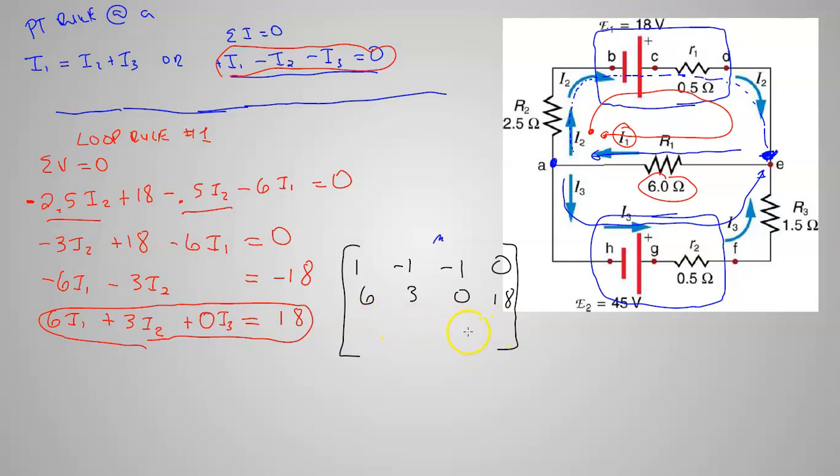And I need one more equation here to finish this thing out. So I got to apply the loop rule one more time. And again, I can pick any loop. I can go in any order, any direction. It is easier to go with the current. So we did the top loop here. We went around this way. Maybe the next thing we should do would be to come around this way. Go down the bottom branch and then back across the middle. So I'm going to draw that loop right here. We'll start right here. I'm going to go down and around and back, and I got a complete loop. And right here I've got enough room to put that one in, loop rule number 2.